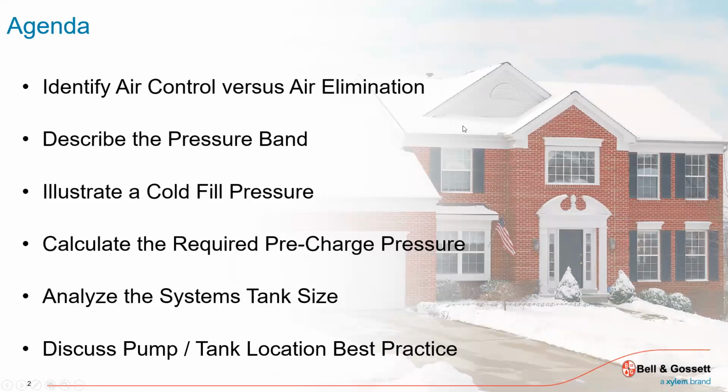We have to have this body of gas to accept the expansion that's going to take place. As you heat water, the molecules expand, they take up more volume. That volume has got to go somewhere. Water's not compressible. Steel pipe doesn't flex, typically.